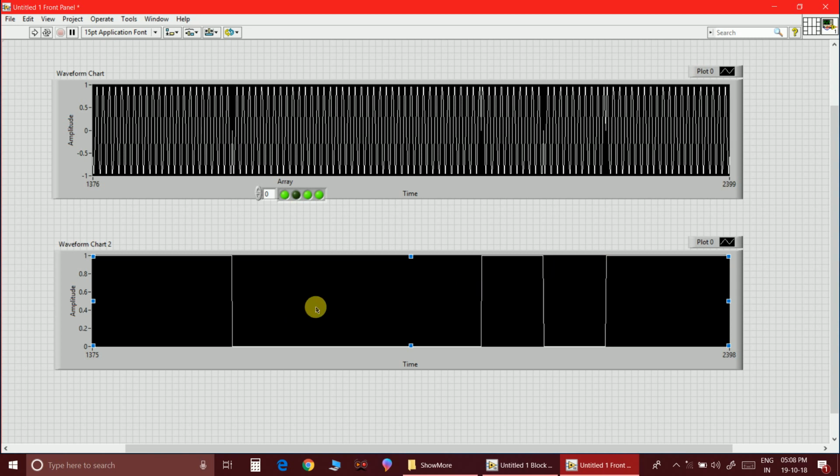If you see the equation, then you get the feel that for data bit 1 you will transmit A cos omega ct, and for data bit 0 it will be minus A cos omega ct. So here also there is a phase shift at every bit transition. With this you can say that a PSK wave can be generated very easily with the basic knowledge of ASK in LabVIEW.